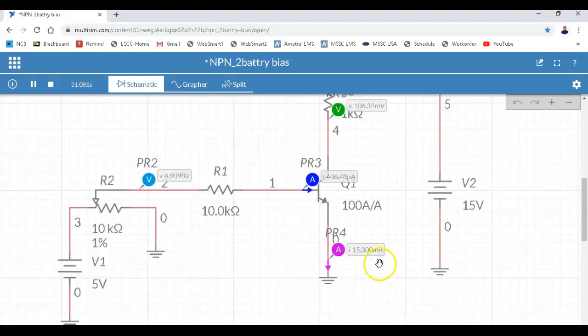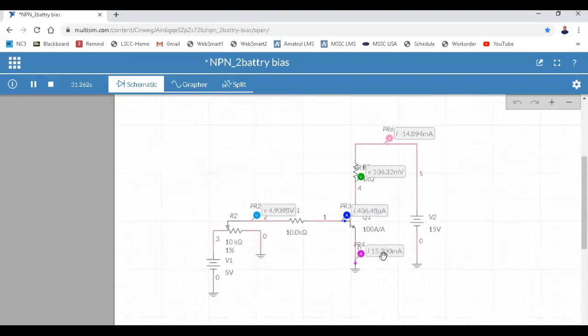So if this right here is a series circuit, sorry guys, why don't this amp meter and this amp meter show me the same thing? This is 0 volts down here, by the way, Brian. That's common, right? So that's 0 volts, and you can't see it. Over here, I have 4.9 volts. I did have a voltmeter right there, so over here I'd see about 7/10, right? But notice this resistor up here is only dropping what? 160 millivolts. So what would I have across the transistor?